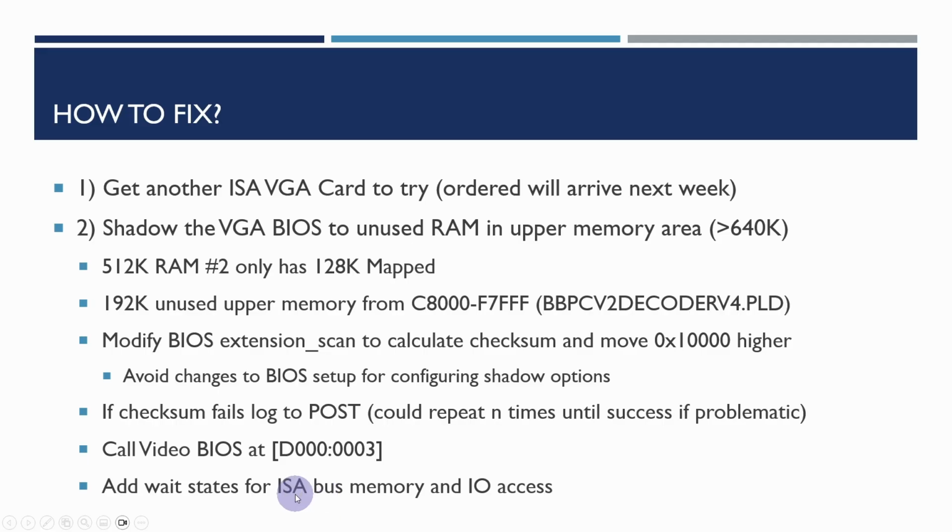However, because it slows down the rest of the computer quite a bit, and even the startup Intel-type sound at the beginning of the beeps is quite a bit slower, I've modified this so that it only runs the ISA bus accesses for RAM and ROM at the slower speeds, and generally all I/O accesses will also be at these slower speeds.